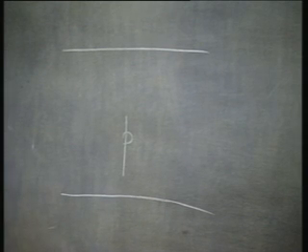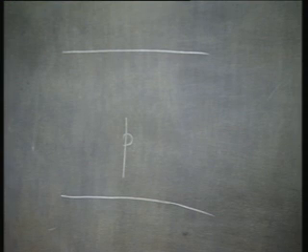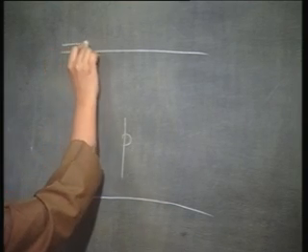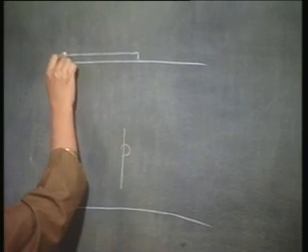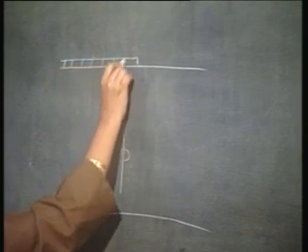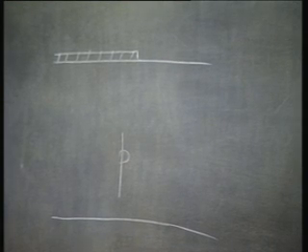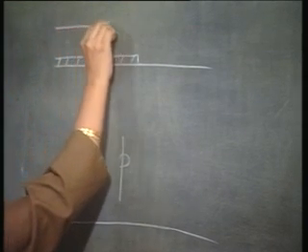Right. Now, your first mask is going to be the Nwell mask, that is, I must dope a certain region in this P type substrate as the Nwell. And how do I do that? I do that by a low cost technique. That is, I protect a certain region of the P type substrate using an oxide nitride mask.